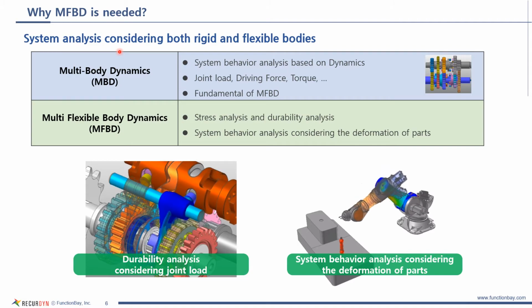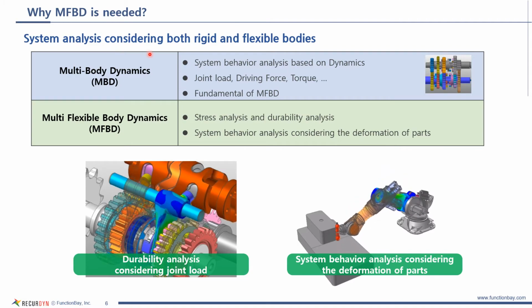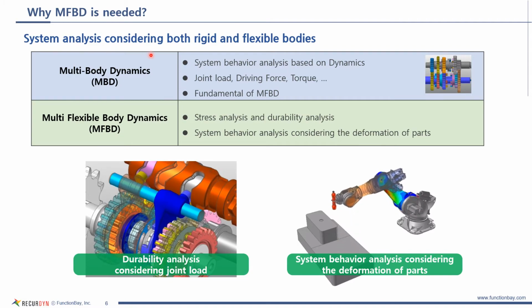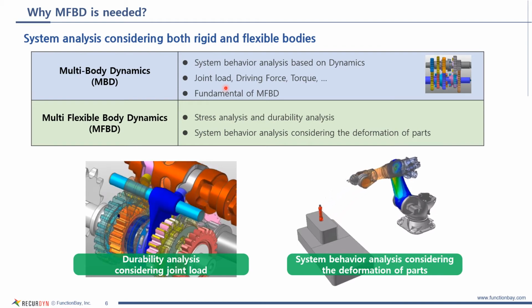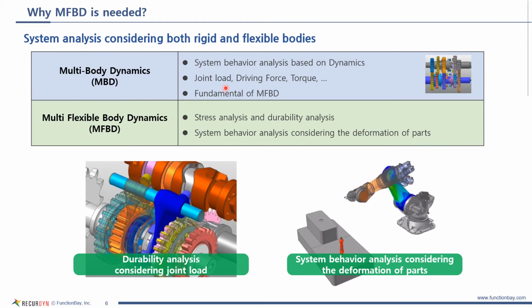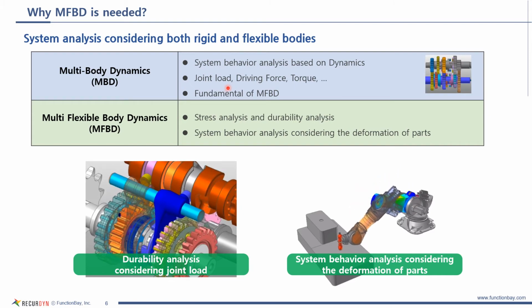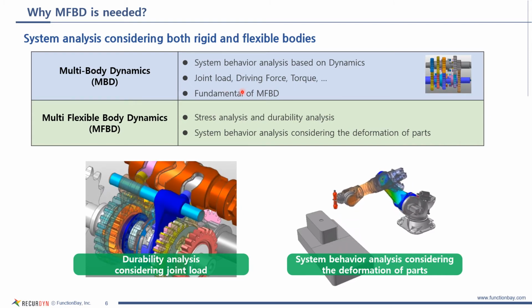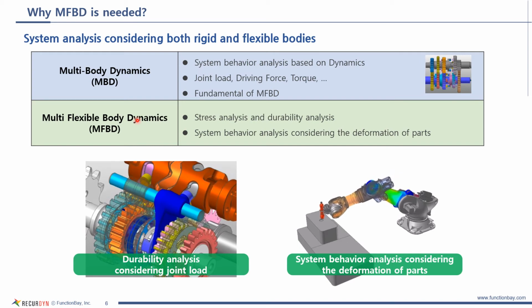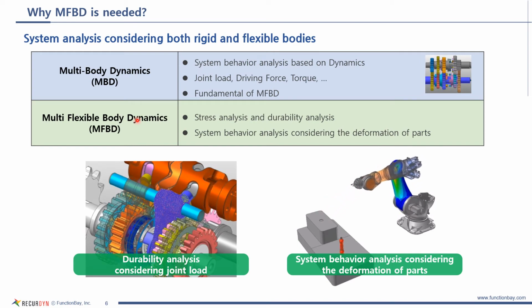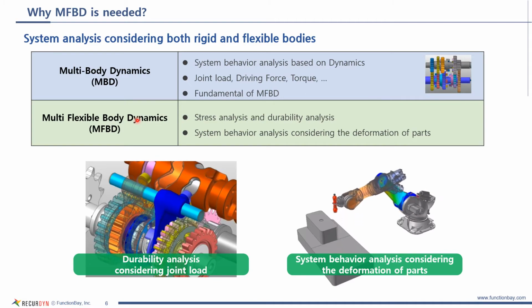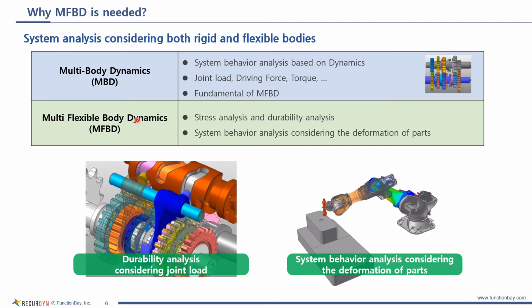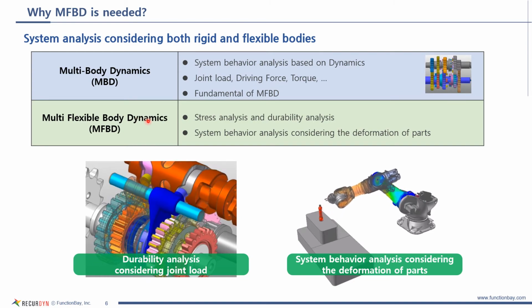Then, why is MFBD needed? MFBD is based on the rigid multibody dynamics. Multibody dynamics can simulate the behavior of a system composed of rigid bodies and also calculate joint loads or driving force and torque. Based on this, the extended version can be MFBD. MFBD allows to simulate the stress applied to the part, evaluate the durability, and analyze the behavior of the system, considering the deformation of the part.